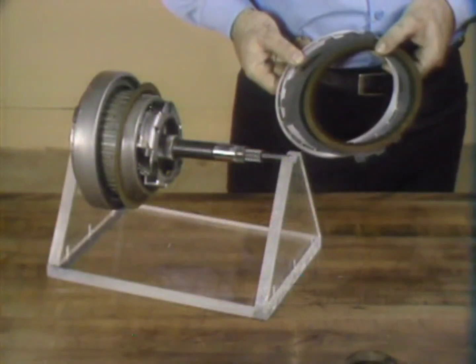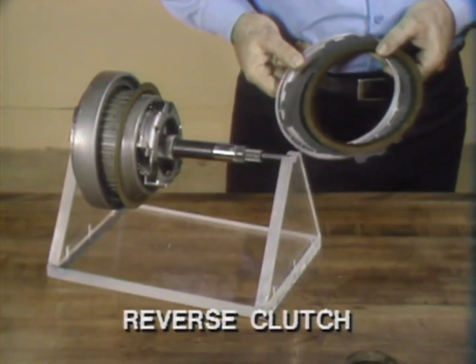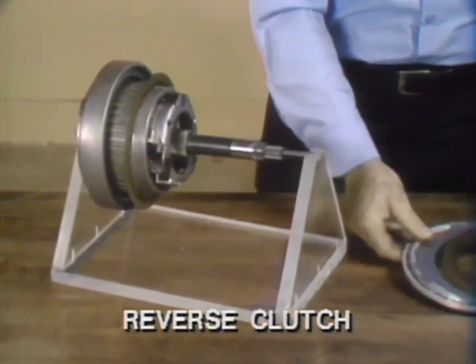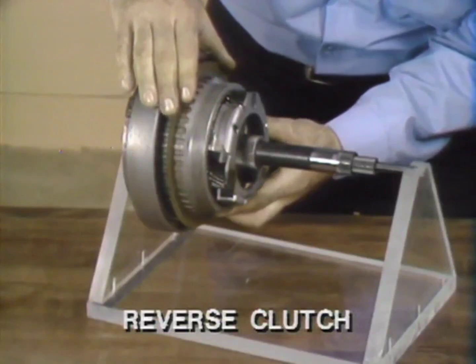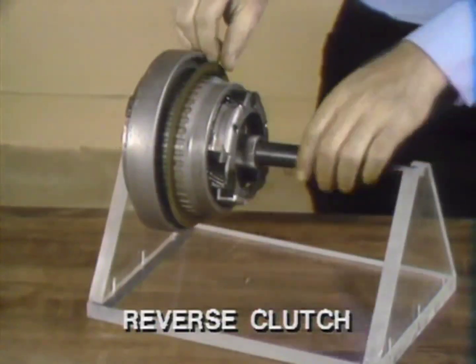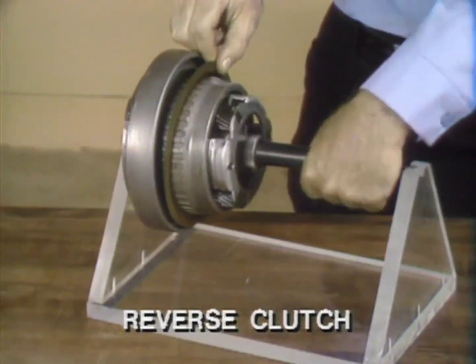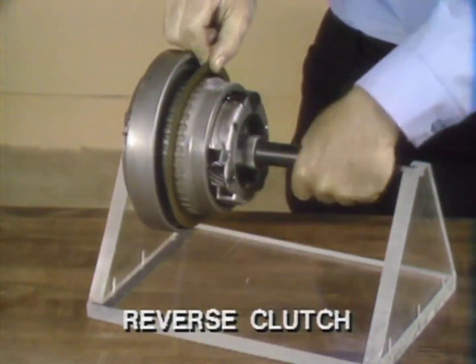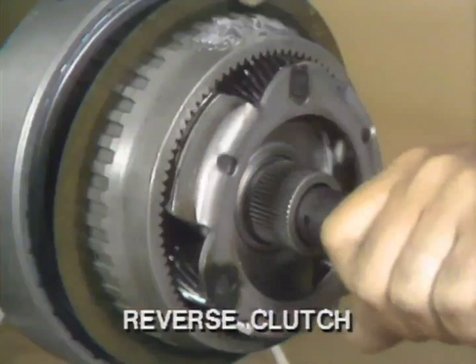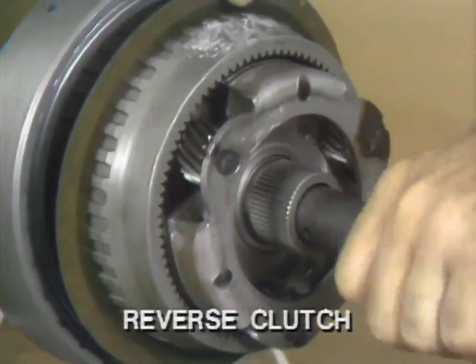Next, let's look at the reverse clutch. The reverse clutch has its steel plates and piston installed stationary in the case. The friction plates with internal splines fit over the splines on the ring gear right next to the intermediate clutch plates. When the reverse clutch is applied, in reverse gear only, the ring gear is held stationary. With power in through the turbine shaft, the long planet pinions are forced to walk around inside the ring gear.